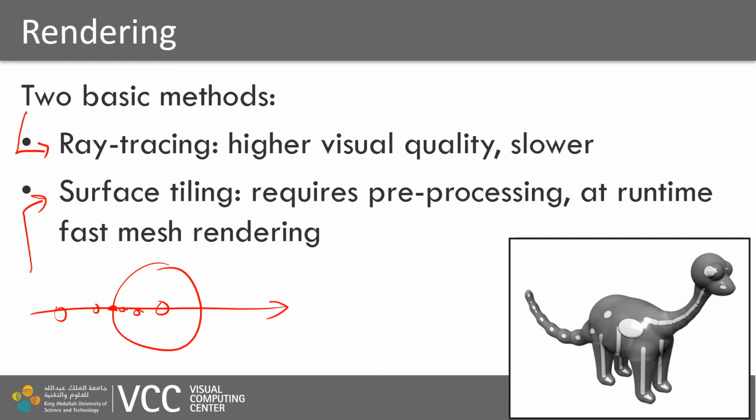As long as the geometry of our implicit blends stays constant, this might be a winning strategy because performance-wise, it will likely beat the direct rendering of implicit representations. However, if we are constantly changing the topology of the objects and so on, positions, and we always need to re-evaluate a new surface and approximate it with the triangle mesh, then the ray tracing approach, the direct method, might be beneficial.